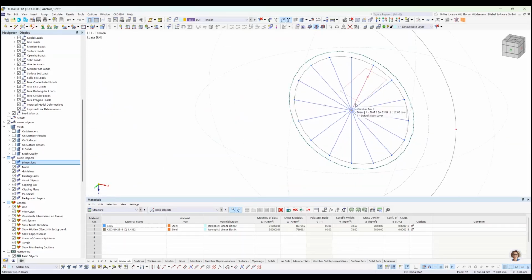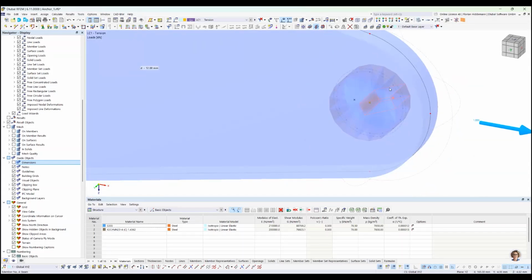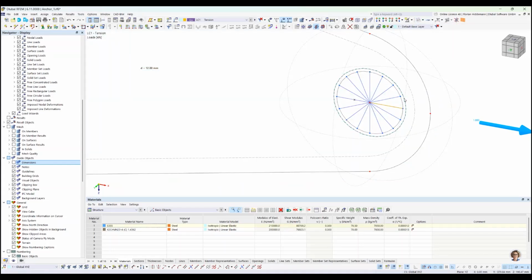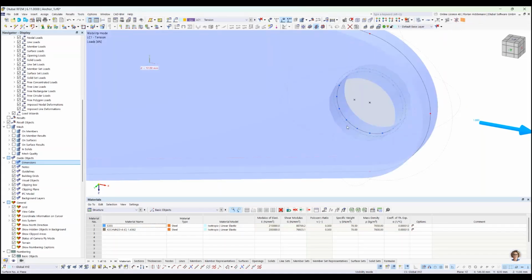As you might see here, we have some nonlinear members. And if I activate the transparent model, you can see that these try to simulate some weak beam section. The model dimensions for these beam elements are chosen in a way that the surface area of the connecting part for the beam end is the same as the area of the cylindrical surface inside of this model.